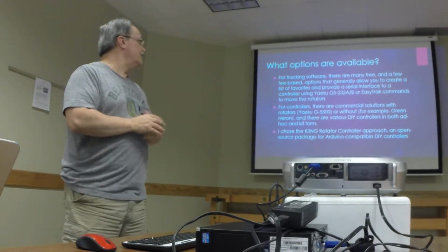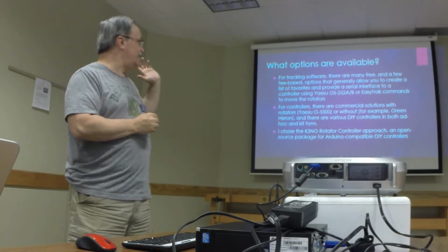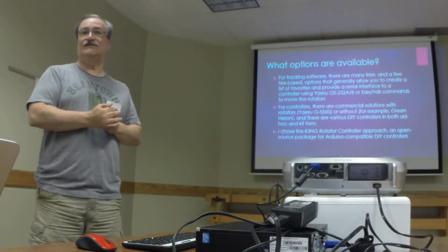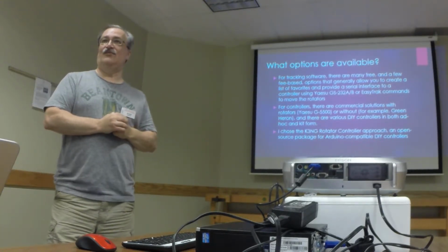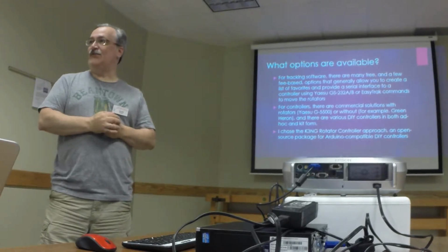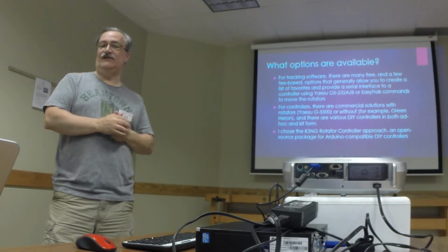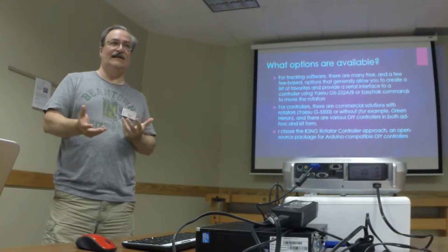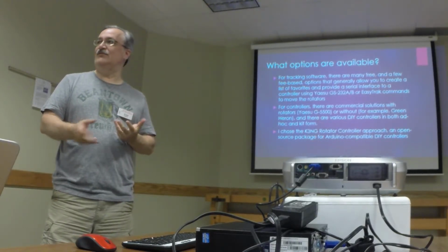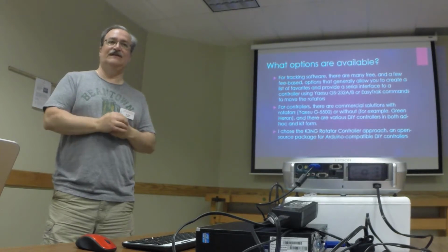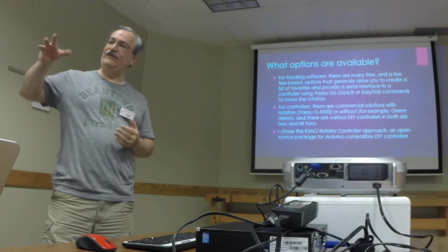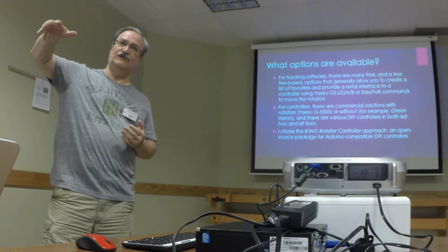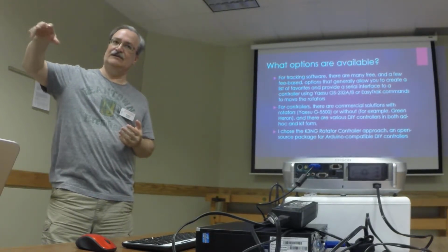There's a bunch of commercial solutions out there, but the Yaesu G5500, which runs $750, is probably the most popular, and it's one of the few out there that's readily available. Some of the other ones are a little more obscure, but companies like M2 Antenna, for example, who makes a lot of UHF, VHF antennas, have both azimuth and elevation combo rotors, whereas two rotors in one, essentially.